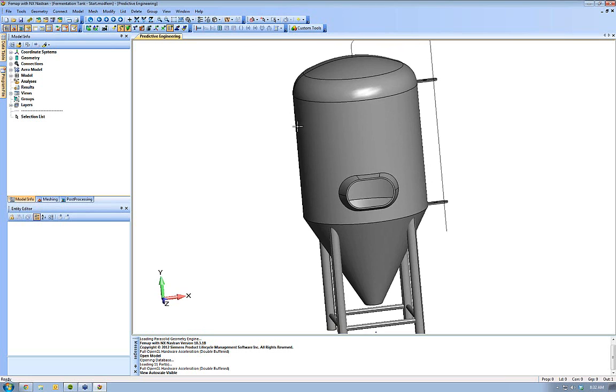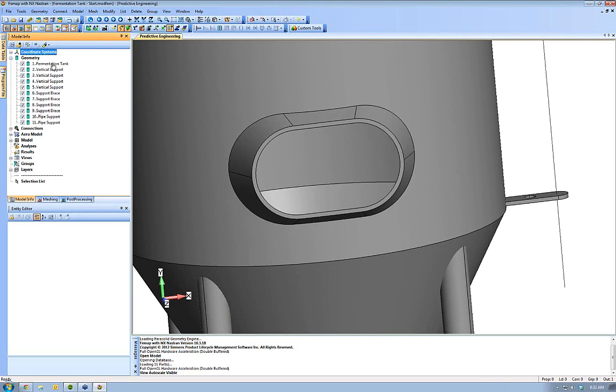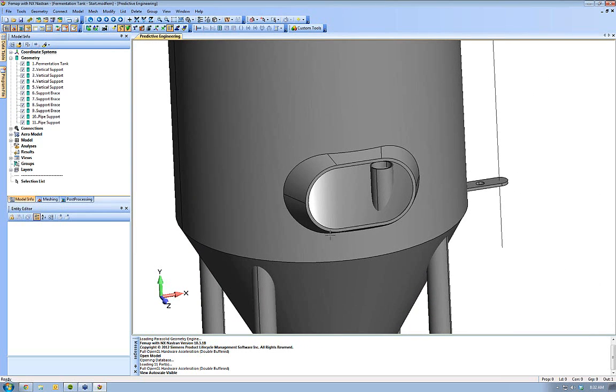So if we look at this, this is a solid body, and I'm going to look at everything through the tree here. It's got thickness, and what we want to create is a sheet solid rather than a body solid. So a sheet solid is going to be made of multiple surfaces, but it's not going to have any volume.